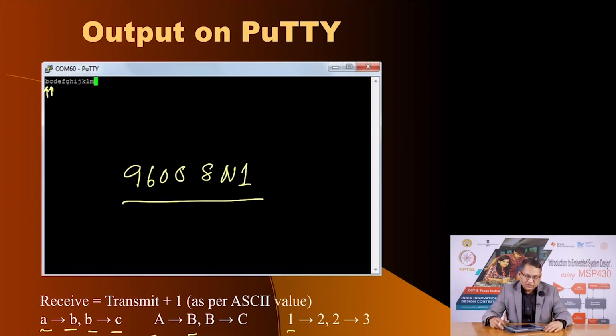So, in this lecture, we have seen how the MSP430 microcontroller can communicate using a variety of protocols, but because of the limitation of the coverage that we can do in this course, we have restricted ourselves to communicating using only the UART. You are free to read the data sheet to understand how the SPI and I2C bus works, and you could use your MSP430 for communicating with external devices within the same embedded system, to utilize the SPI and I2C bus also.